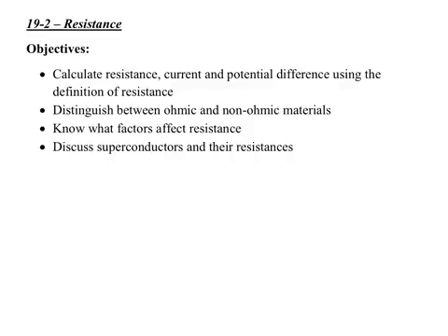That's like what you see on this TV show, somebody's trying to stop the flow. It's not possible. Good luck. It's not going to happen. Especially now the water is flowing out, your hand's going to slip. It wouldn't even be possible. What you do is you find the source of the water flowing to that location and you shut that valve off. So you have these safety valves at several locations along the way in a piping system.